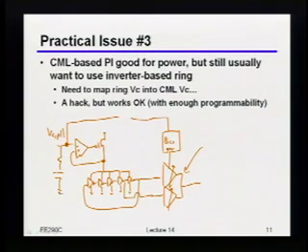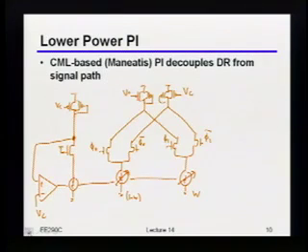Okay, so just one, let's say, minor detailed thing, which is this control voltage here is really referenced to ground, right? So in other words, when the control voltage goes up, the frequency goes up, okay? So if I'm going to be using that same control voltage for this bias generator kind of thing, that's why you have to flip it over, okay? So your programmable resistor will now become an NMOS programmable resistor, right? And the current source will be the PMOS, okay? So when you really do it, you typically will take this and just flip it over.